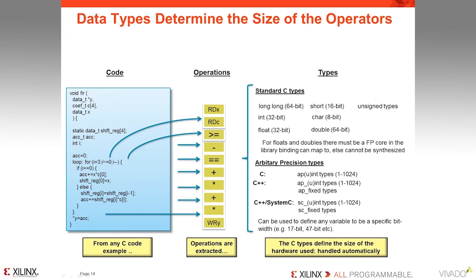And this is one of the greatest advantages of using Vivado HLS. For example, if the user was designing a FIR filter, and it was very important that the signal-to-noise ratio, two things. It's very important that the multiplications were only 12-bit, so that everything could be accumulated into a DSP48. The user could use these exact sizes in the C code, and more importantly, the user could then simulate this C code to confirm that they have all the correct values. They could double-check their signal-to-noise ratio, and they can do all their analysis in C, which runs much, much faster than RTL simulation. Once they're happy with that, they can simply synthesize that and get the exact same behavior at the RT level.